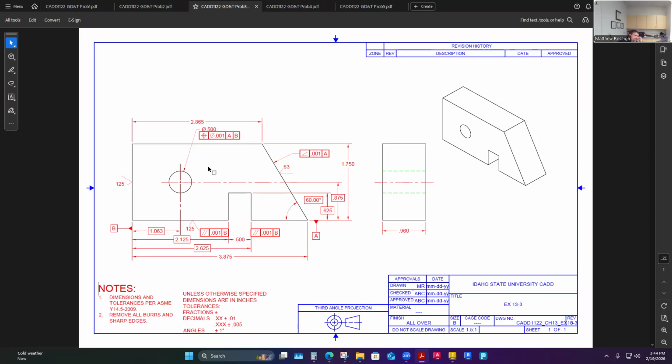It doesn't have the dimensional tolerance given for the hole. I think I will express what's assumed here as a plus minus tolerance. I don't know, just because I think I can do the math when they're closer together, so I kind of like to see it. But I could be wrong on that, and maybe I'm over implying the same tolerance. But this is a regardless of feature size tolerance.